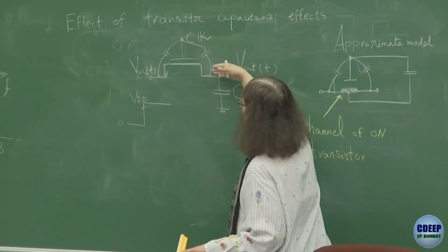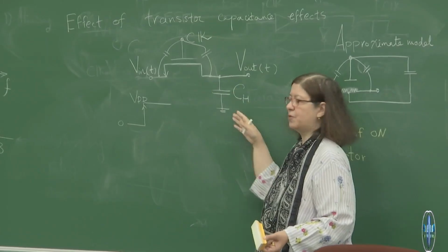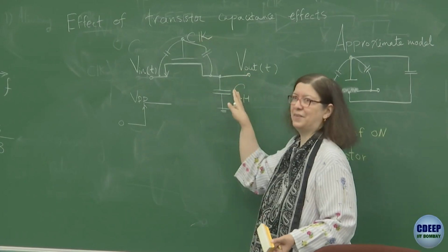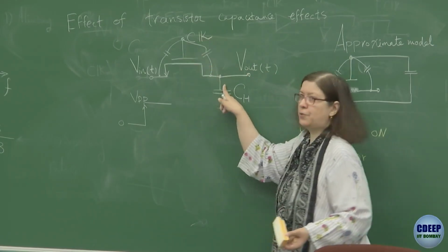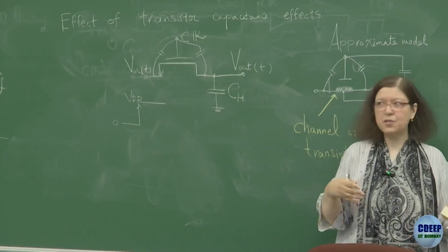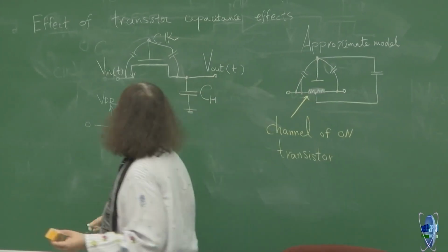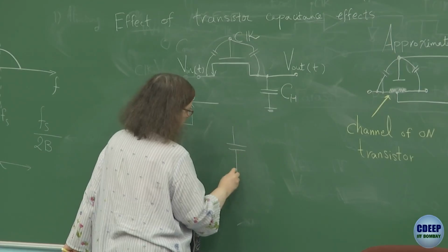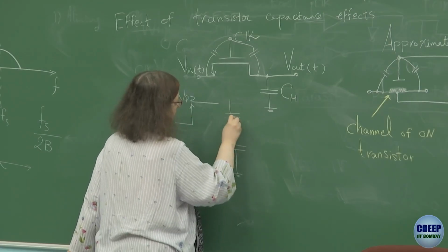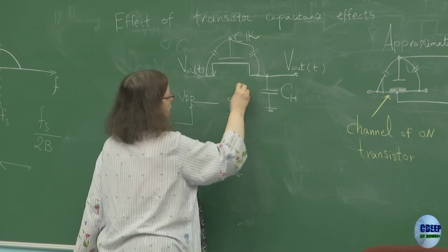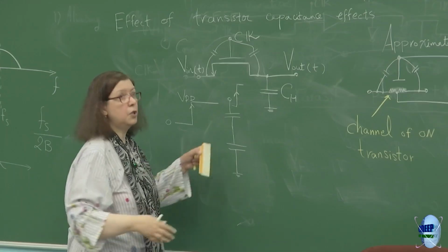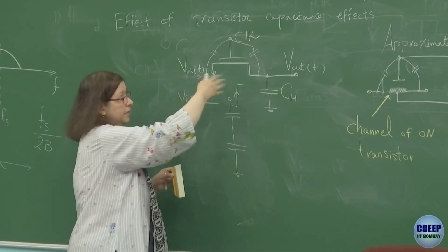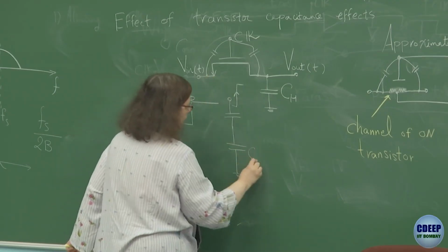So you see this parasitic path. Therefore, if there is a transition here, when there was no capacitor here, there was no coupling. Now the clock node and output node are coupled through a capacitor. So right at that instant, if the clock is very sharp and quick, you have a condition like this. This is the edge, and specifically I showed the edge because this is not true for all instances, because we have a capacitor on the transistor on the left. We cannot ignore it. I'm just talking about a particular edge.